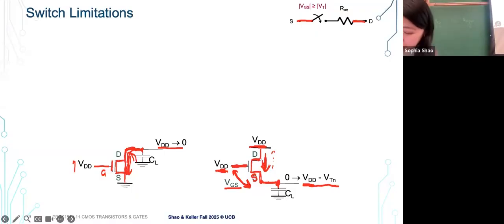So before, the output node was connected to the drain side, so we could fully discharge to 0. But now, when the output node is connected to the source, that's the threshold voltage difference we have.